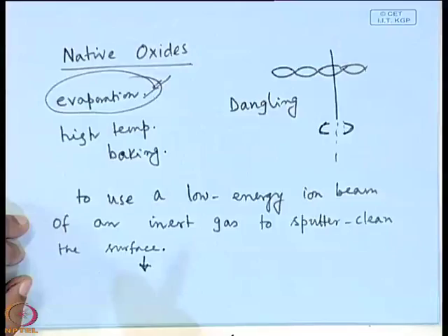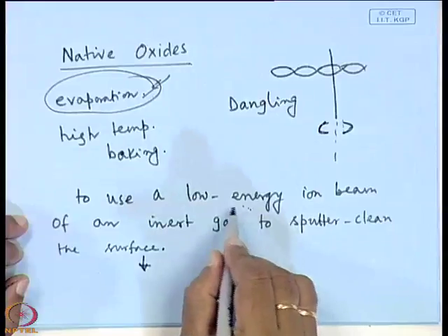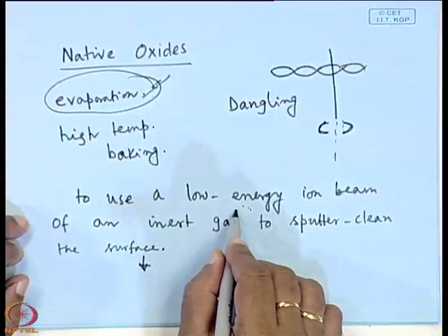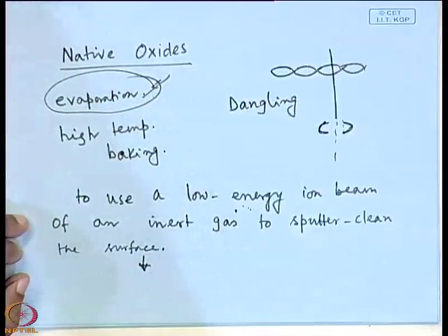Remember that when we sputter something, whatever be the energy, I have written that it is a low energy, there will be deformation of the surface. So, that means we have to make some low temperature annealing that we have mentioned during our discussion on diffusion and ion implantation.